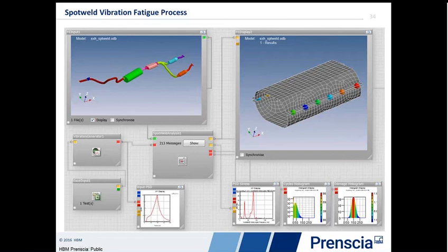And again, same basic input in terms of the PSD. Here the dynamic response is very, very different because we're looking at this aluminum heat shield that we're exciting versus the exhaust system. And again, using the PSD of stress to count cycles and calculate the fatigue damage.